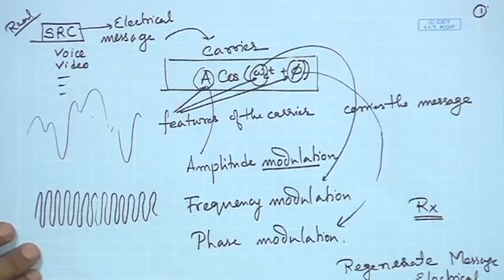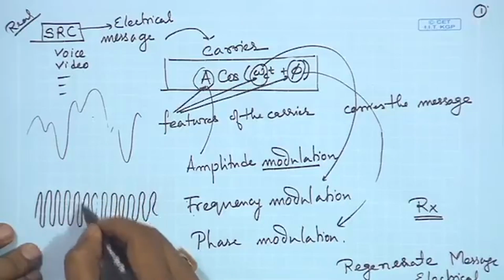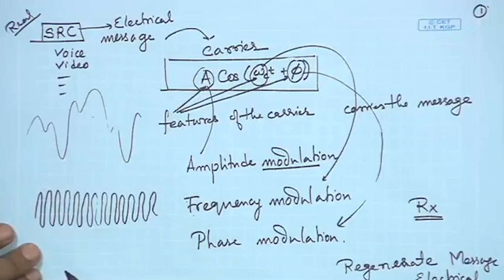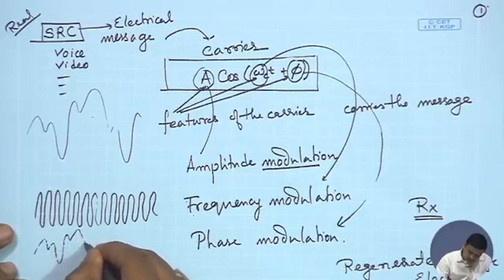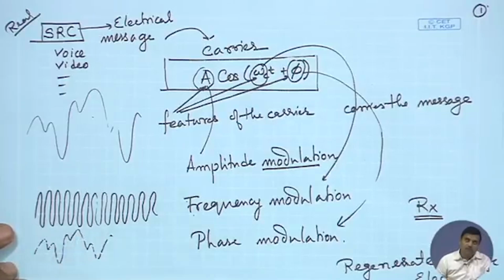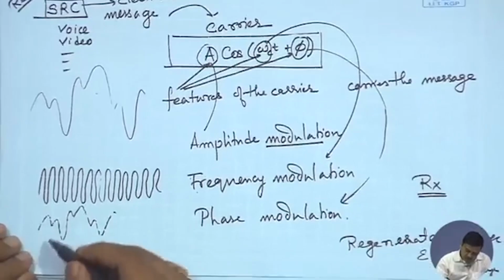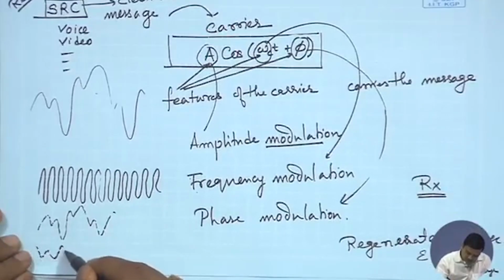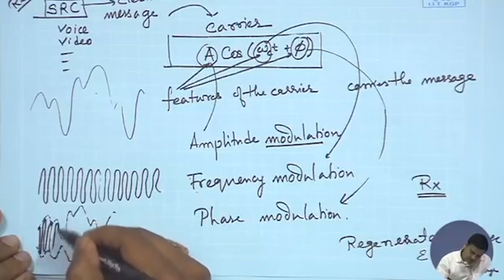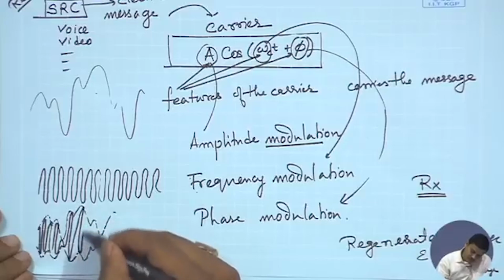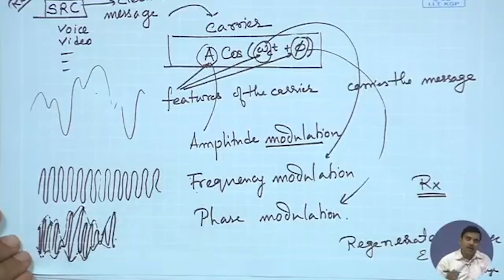You can still do it, but generally you would not allow the signal to go to the opposite phase, and you would limit the amount of modulation. Your modulated signal would occupy some shape governed by this envelope. It's not an exact picture, but you would have an amplitude modulated signal which looks like this, and it is quite easy to draw.